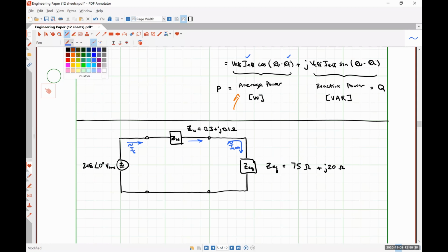But we would also need to know the RMS voltage over our load, V load like so. Because if we want it over this particular thing, we need to know potentially both the voltage drop over it and the current flowing through it, just like any other thing. We're just treating all of the loads being drawn by the house as effectively one generic circuit element. But if we want the power delivered to a particular circuit element, we need to know both the voltage drop over that element and the current flowing through that element, or other information about it.